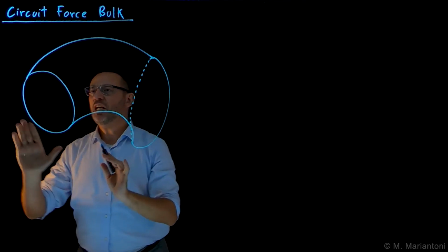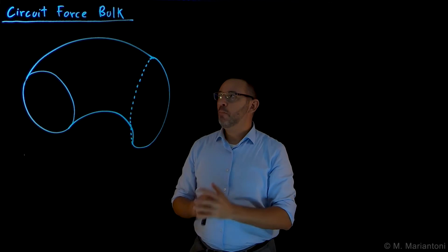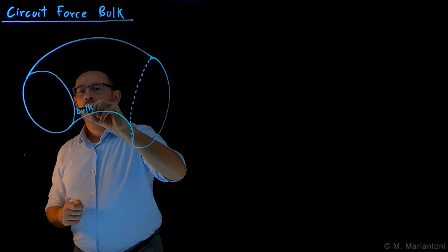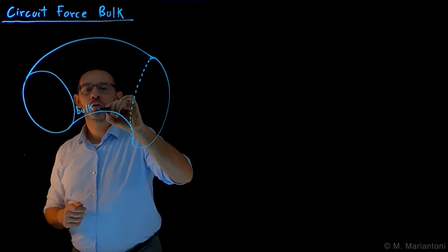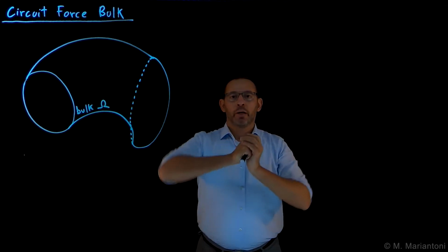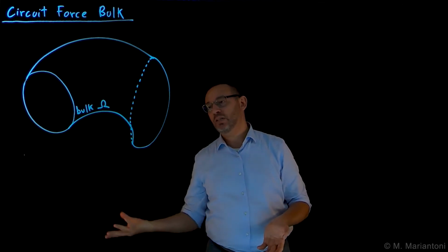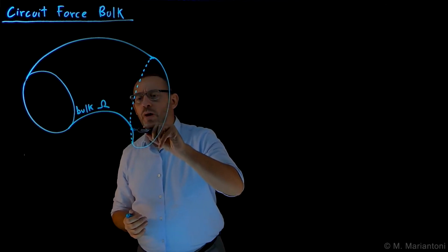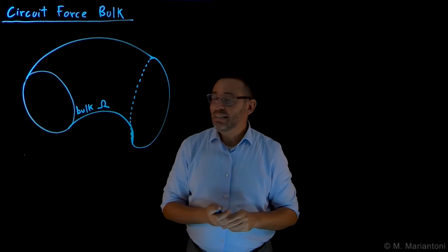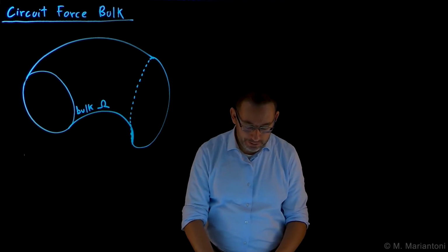This is the cross-section of our wire, and let's say that in this case, the procedure we need to do in presence of bulk conductor, so this is a bulk conductor characterized by a volume, a volumetric region, capital omega in the three-dimensional Euclidean space. So what is the procedure we need to follow always when considering currents in presence of bulk conductors? We have seen this in 242 already, where what has to be done in this specific case is that we need to split this object in an infinite set of filiform, infinitesimal flux tubes.